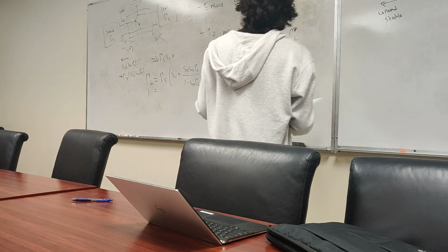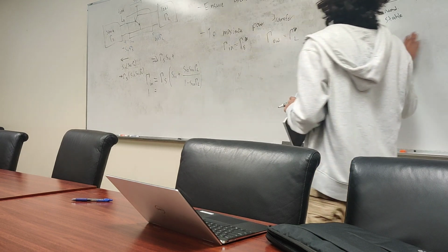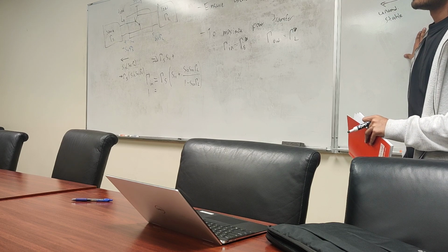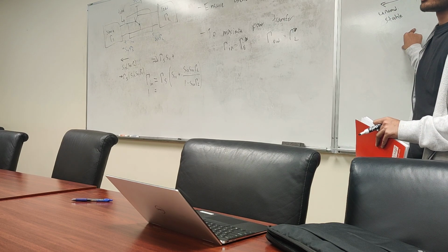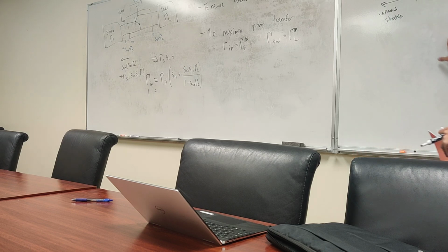So the other cool thing is there's no trade-off here between unconditional stability and max gain. If something's unconditionally stable, you can still extract the maximum gain from it. Typically, you expect it to be a design trade-off. Hey, we make it stable, but don't get as much gain. No, we can still get the max gain. So that's something to be aware of.